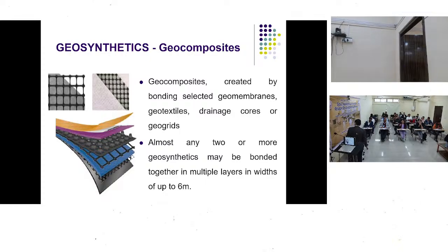So they installed a geomembrane on the upstream face of the dam, and in order to handle whatever water is contained at the dam bottom, they installed a non-woven geotextile behind this geomembrane. There were two purposes of this non-woven geotextile. Number one, it was giving way to the water. Secondly, it was also protecting the geomembrane from being punctured, because this was a stone masonry dam.